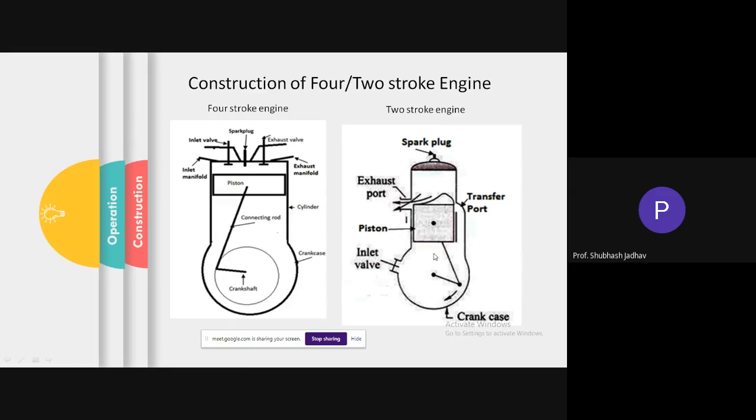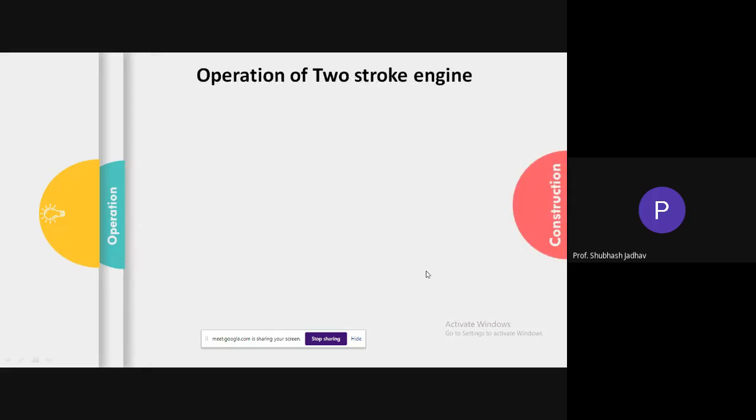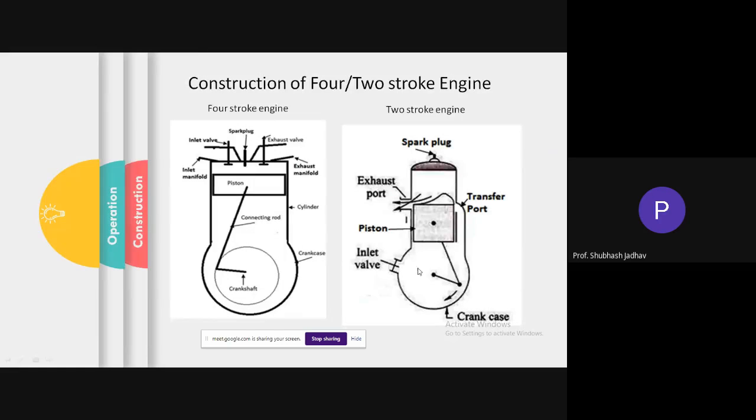And this will happen when the piston is moving up. Why will this happen? Because the piston has moved up and a negative pressure has been created in this region, and there is positive pressure on the outside, that is atmospheric pressure. So here we have created a pressure lesser than atmospheric, and that is why the fluid, here the mixture, is a fluid. A fluid can be a gas or a liquid. So the fluid is now moving in this direction, through this particular inlet wall, and is going to come in and occupy this particular region. So this region is now filled with air fuel mixture.